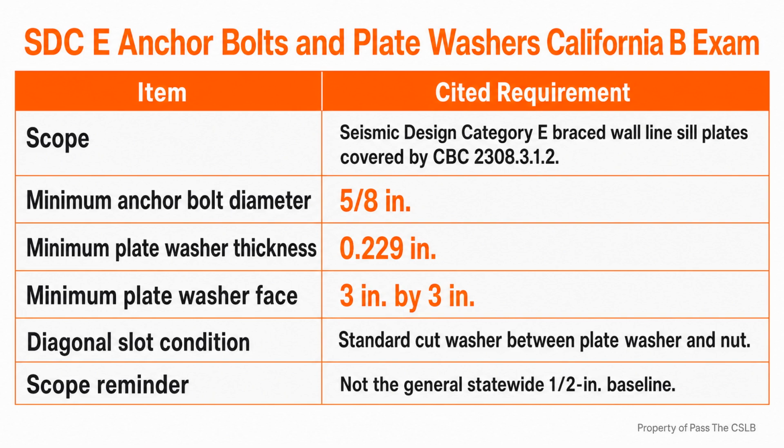Then I follow the wall to its base, checking the panel fastening, specified wall framing, hold-down locations, sill attachment, and foundation anchorage. I do not let a large piece of hardware distract me from small required fasteners. The most impressive hold-down on the project cannot compensate for missing diaphragm edge fastening above it. In the same way, perfect diaphragm nailing cannot compensate for an anchor bolt that lacks required embedment or sits outside the permitted end distance. Each link has one job, and the path depends on all of them.